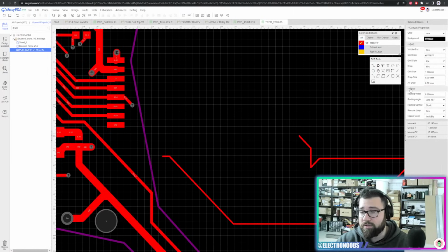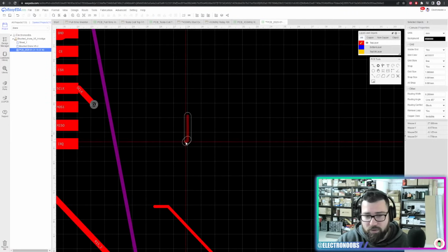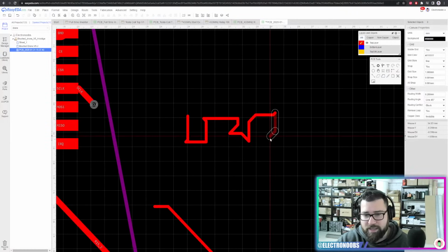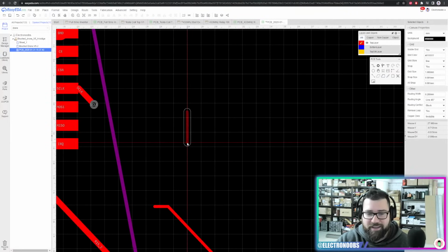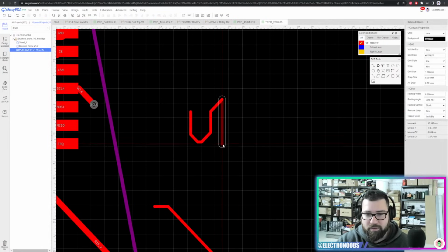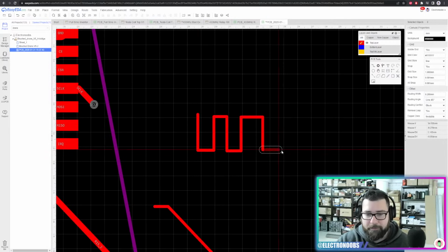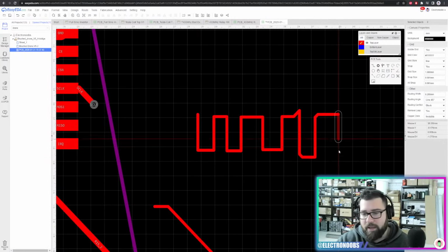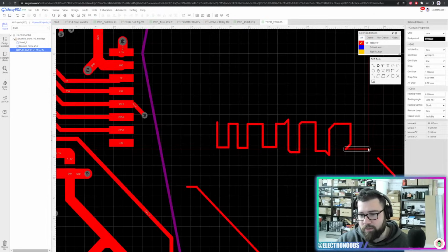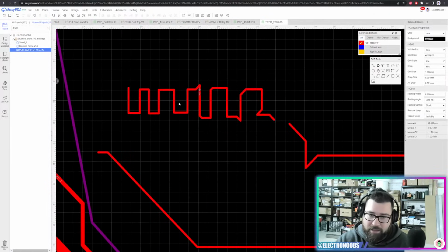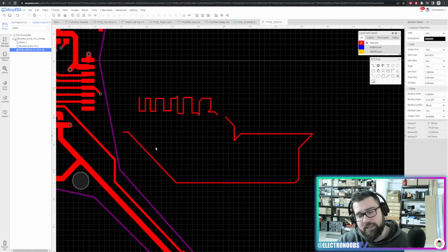So usually what you will see on some PCBs is some sort of zigzag. So instead of just going straight here, you will go like this and make some sort of zigzag. Actually, with 45 degrees it will be better. So you can make some sort of zigzag like this. This is very ugly, sorry. Anyway, I'll do this very fast because I don't want to waste any time. Then the length of this one and the resistance of this track will be the same as this one.